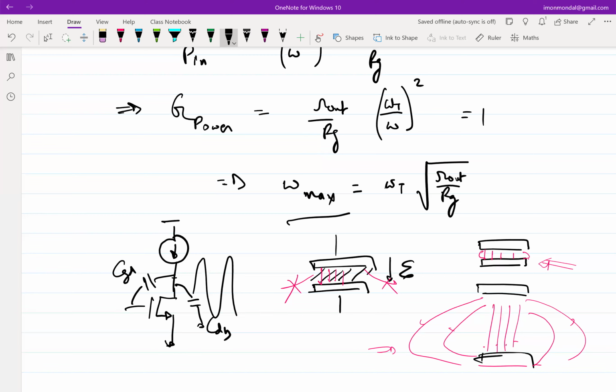True, but to some extent that is still in your control. You can increase W. Again, there is a trade-off, but you are thinking in the right direction. That's another problem. Yes, we are making the gm bigger. So essentially, we are going back technology nodes, you can think of it.